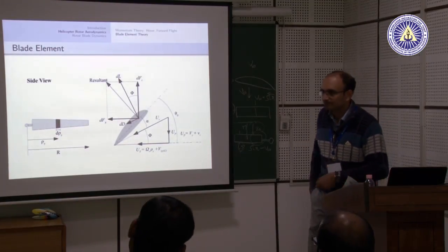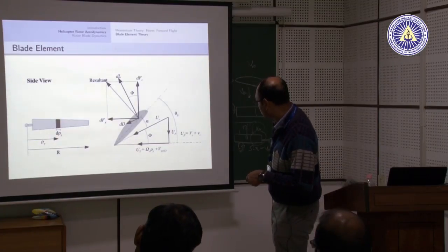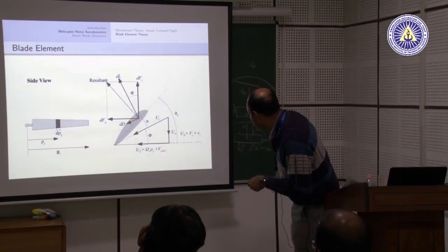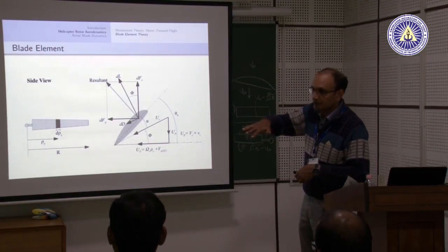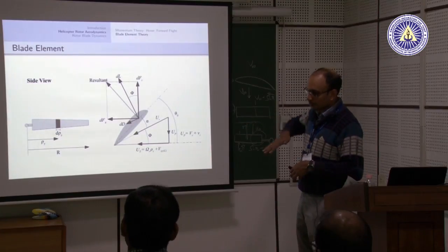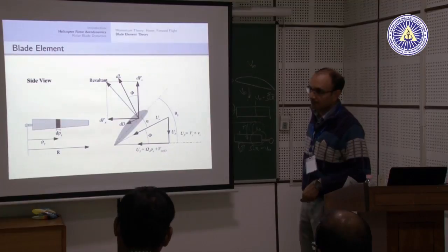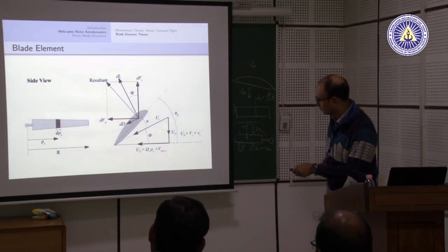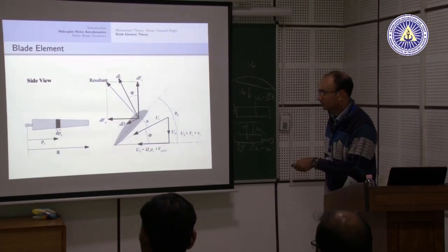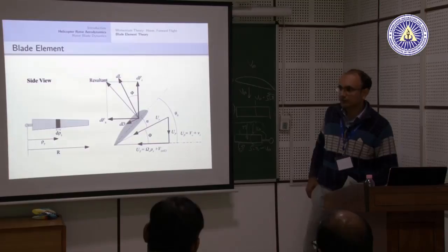Okay. What is this Vxyc? So this is if my helicopter is flying in a general direction. My helicopter may be flying in any arbitrary direction, so the component of the forward velocity will be here. This is some general component, but normally it will not be there. You will only have this. Likewise, what we see here, v infinity, is that same v infinity.